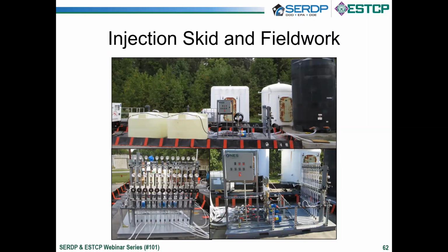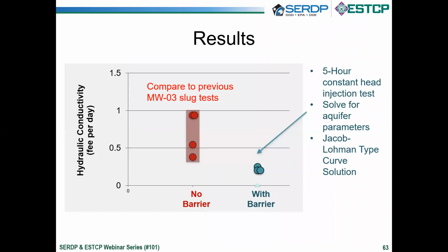So the mixing process in general is a bit more complex than standard injection-based remediation projects. And this is because the injection skid needed to mix 3 fluids at very specific concentrations. It also needed to deliver multiple locations at the same time. And we also wanted to ensure that the grout didn't harden within the skid before we injected it. We finally also did some on-site gel tests using actual site soils, which showed that both grout types gelled with gel times around 2 to 2.5 hours.